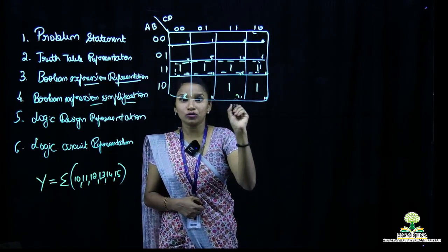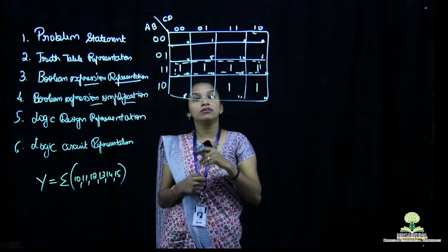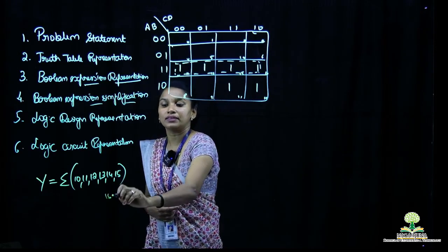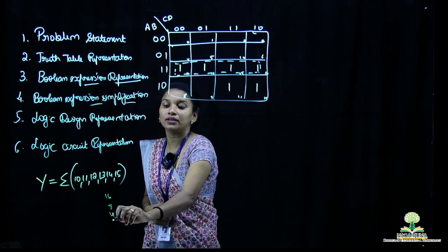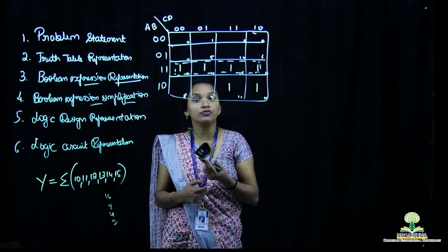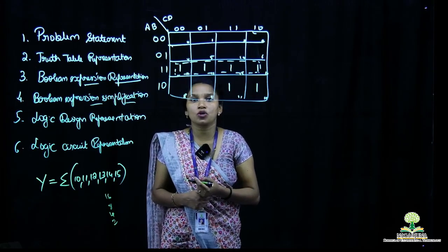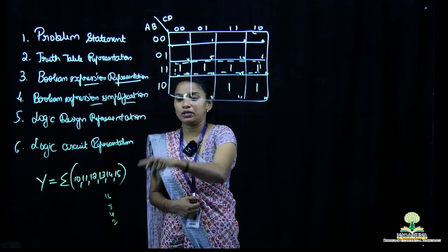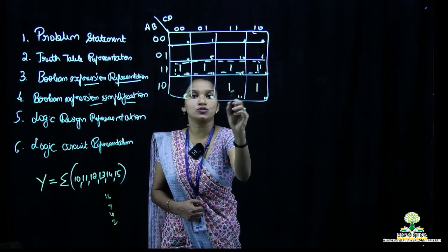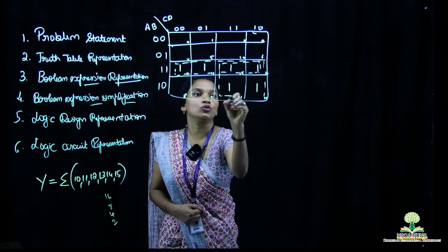So now coming to the grouping of this particular K-map, we always know that in the K-map, you will always have to aim at the highest grouping. We look for a grouping of 16, then followed by 8, then 4, then 2 or 1. A single grouping is also possible if there are no groupings left. Now 16 is not possible here, 8 is not possible. Now we have a grouping of 4 here, 1, 1, 1. Then the rest, the place values of 11 and 10, are vacant. Even here this can be grouped, which can be a group of 4.